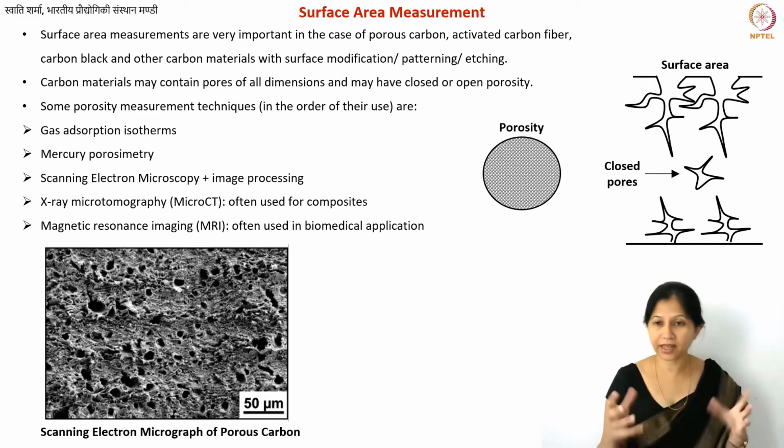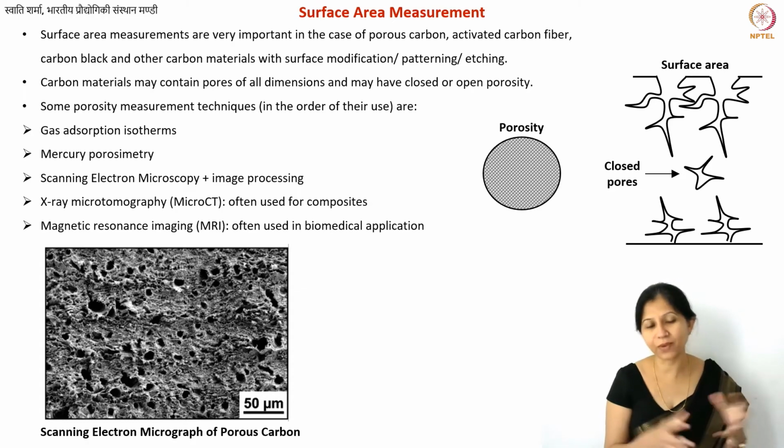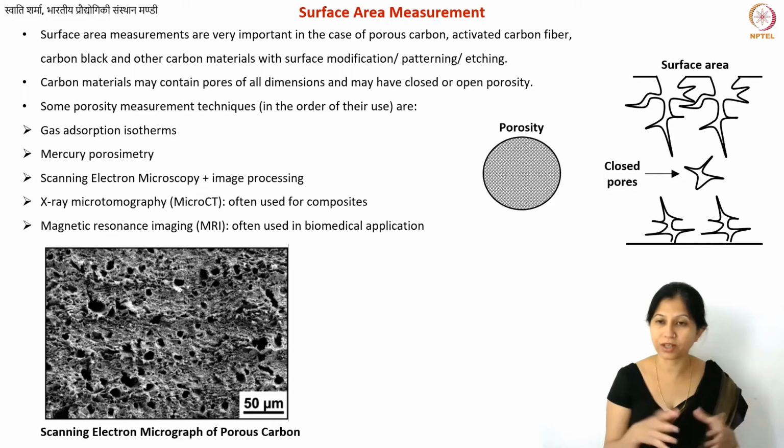And then you will see that there are some pores. Now, based on the contrast in this image, you can perform some image processing, and that will give you some idea of what is the surface that is covered by the pores, not volume, surface, because right now we are talking about 2D. You can extrapolate it to volume. And I'll also tell you a trick that will help you understand the volume porosity.